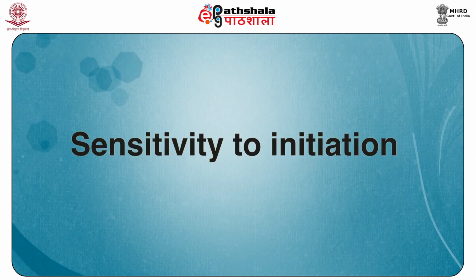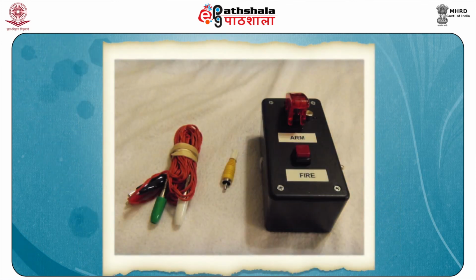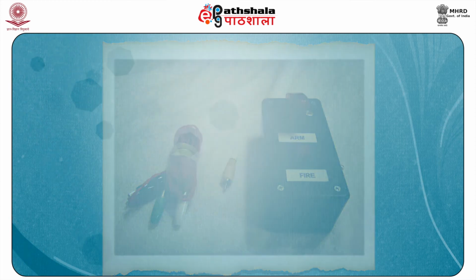Sensitivity to initiation is defined by the power of the detonator which is certain to prime the explosive to sustained and continuous detonation. Velocity of detonation. It is the speed with which the reaction process spreads in the mass of the explosive, which is a significant feature of an explosive and differs according to the kind of explosive.